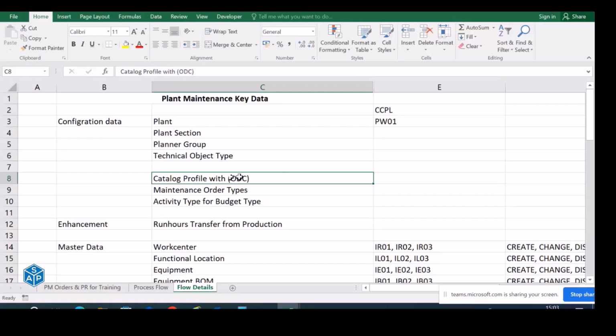That means overload, belt torn, wear, bearing failure, oil level low, motor overload, motor drive healthy, like that. These are also already defined, and have been mapped to equipment also. Whichever new equipment you are creating, you have to map this.